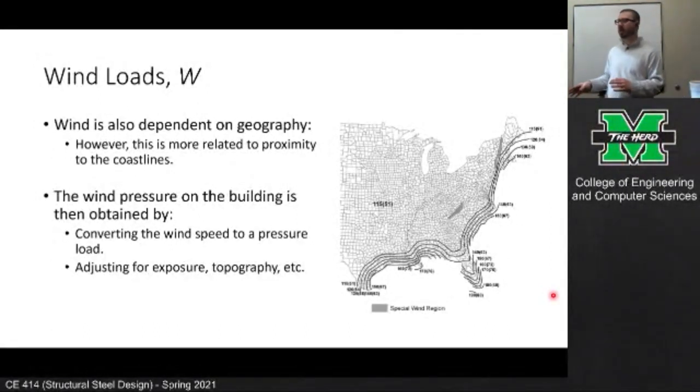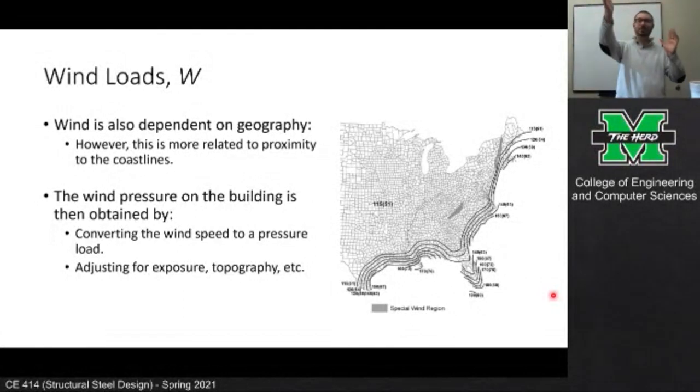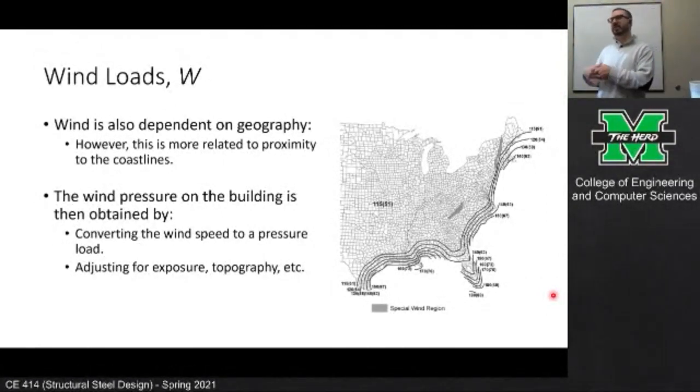And risk category 4 is like police, fire stations, hospitals, 911 call centers, anything where if the structure fell down, that's going to impact everybody. Like if the hospital experienced a structural failure, that would affect the whole city. What you'll find with environmental effects is we actually increase the environmental effects based on their risk category as well.